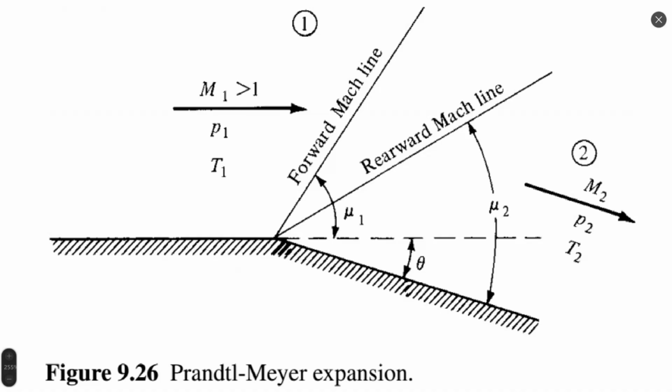And in cases where you can find oblique shock waves or bow shock waves, you in most of cases can also find such a flow as expansion wave. Prandtl-Meyer expansion wave. Such flow is different with respect to supersonic shock waves because it's, let's say, an opposite process.